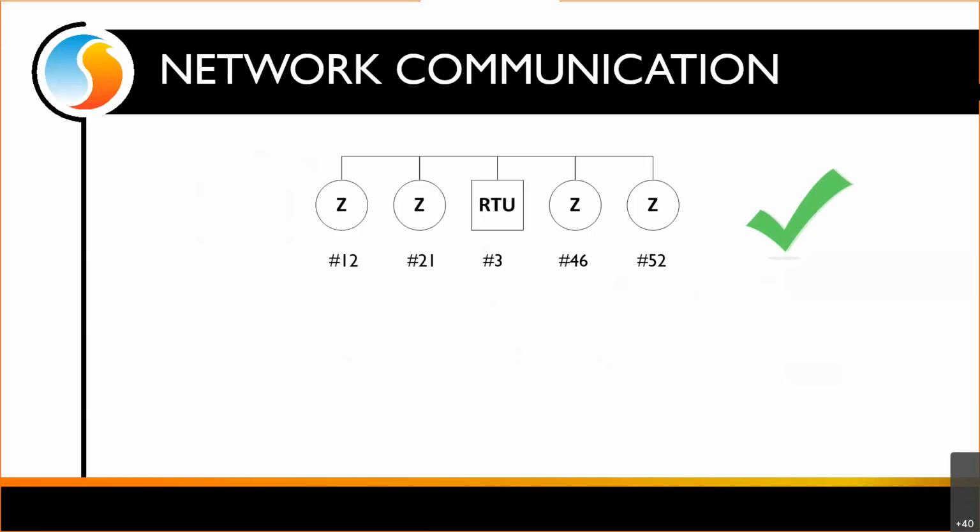And maybe just to help people out, we do think that it is easier when you do address the controllers in sequence. So, for example, I typically advise people give the rooftop an address such as 10, 20, 30, 40, and then the zones of, let's say, rooftop number 10, well, then the zones would be 11, 12, 13, 14, and the zones for rooftop number 20 would be 21, 22, 23. And so that way we're able to pair together, if you will, which zones should be with which rooftop controller.